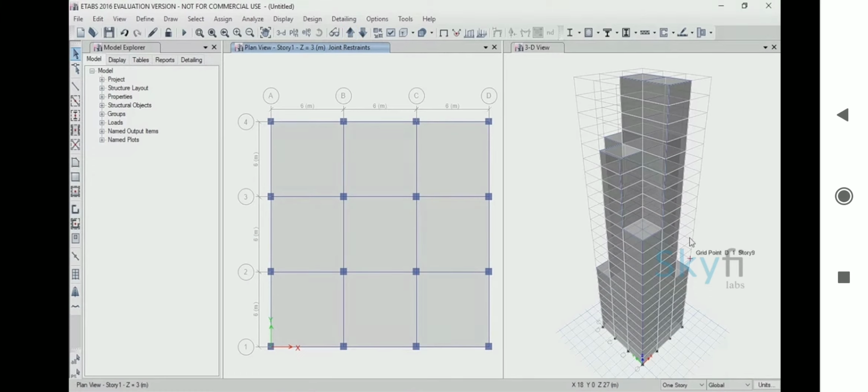You can notice that the building section is not uniform throughout the height of the building. Thus the windward-facing shells will be in more than one elevation section. If we consider that the wind is blowing from the left side, then it will directly hit some claddings of the section A, and some claddings of section B, depending on the story. So you have to carefully select the claddings section-wise, with respect to each side of the building. You will understand more clearly, as we proceed with the steps.